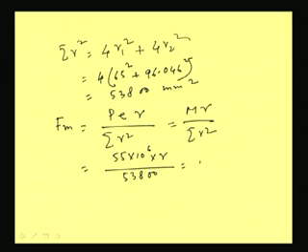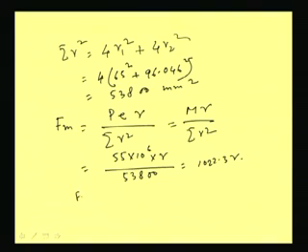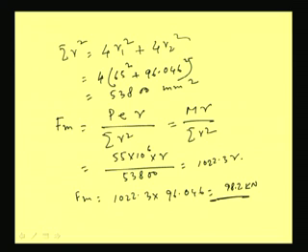So, this is coming 1022.3 R. Now, as you have told, maximum force will develop at the extreme position of the rivet, as you have shown. So, Fm will become 1022.3 into R, where we will take 96.046. So, this will become 98.2 kilonewton. So, this is the force which is developing in the extreme rivet due to the moment.